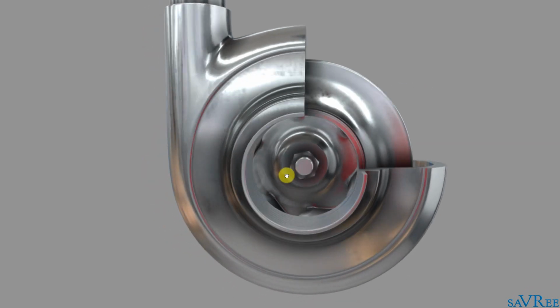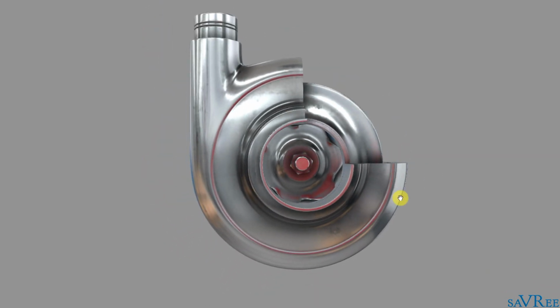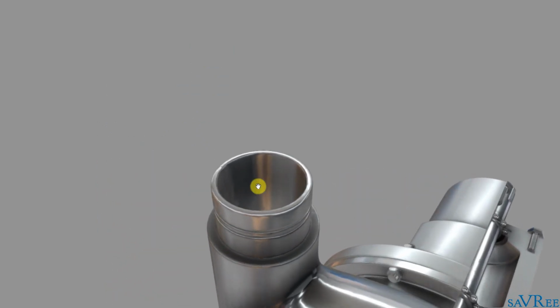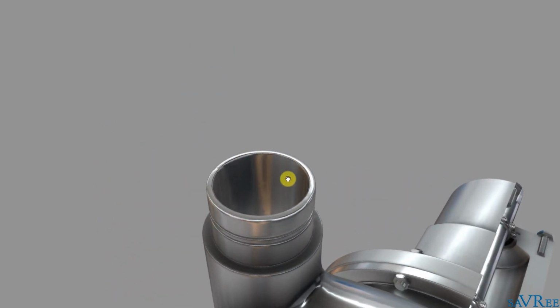The volute casing surrounds the impeller, and it looks a little bit like a snail. The liquid comes around, and as it comes around, it's going to be discharged at the top of the centrifugal pump through this section here, and we're going to send the condensate through a heater or a series of heaters before it reaches the deaerator.